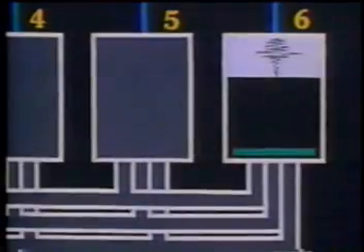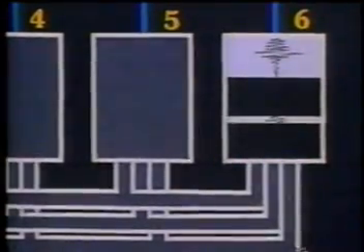Upon a transmit command from the connection table, this digital PCM word is placed upon the parallel digital bus. And upon a receive command in the next time slot, the PCM word enters the assigned extension channel where it is decoded back into the original analog sample.